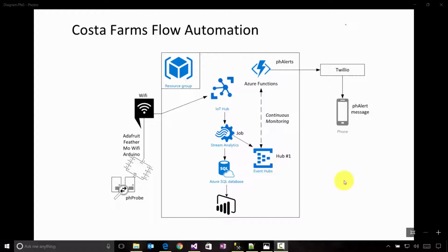So we start with a pH sensor probe that we have hooked up to an Arduino Adafruit Feather on Wi-Fi. It's taking a reading of the pH value. We take that value and package it up as a simple JSON object with a couple of different fields: a nursery ID, a row ID, and what type of sensor. So in theory, we can use this for any type of sensor. We also send what the min value threshold is, the max value, and then the current value. We use that later on, which we'll show you.